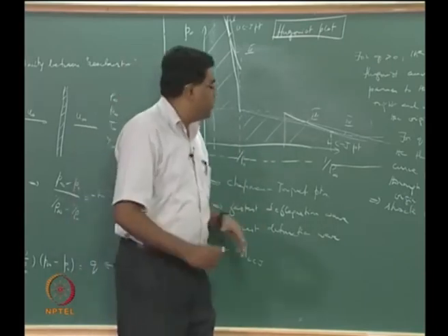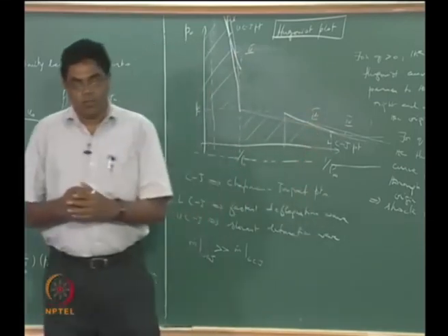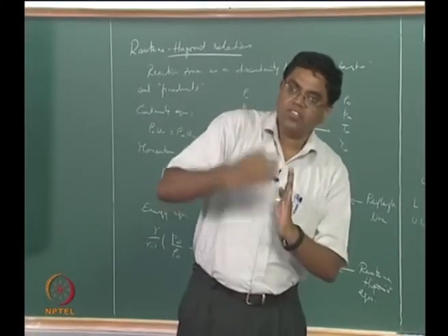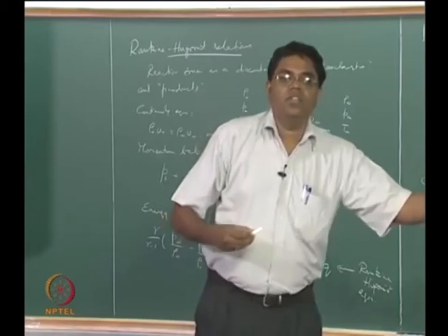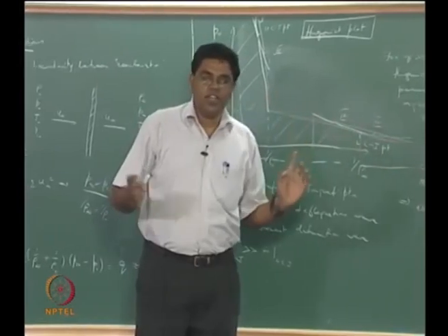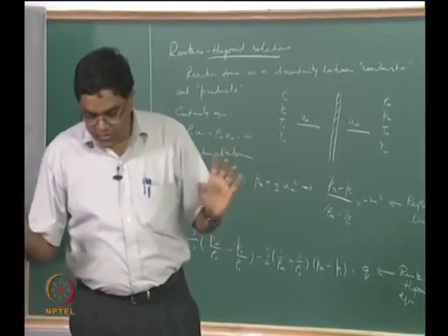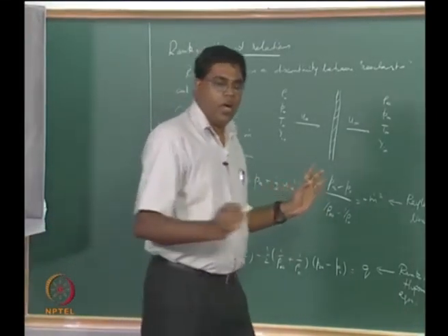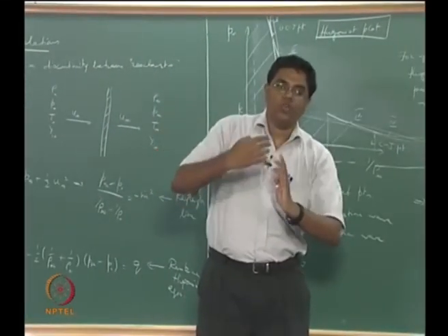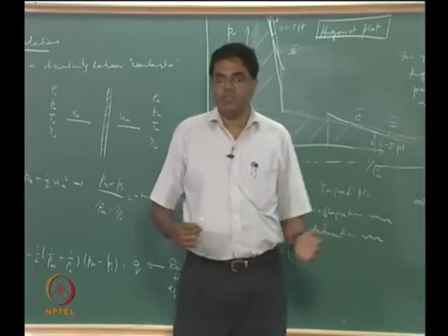Correspondingly, just like how we found in the case of UCJ, what this means for the LCJ is the approach velocities for the reactants is subsonic, alright, but the flow accelerates through the wave to exactly sonic conditions beyond for the LCJ. Now if you really think about it, this is getting a little bit more fascinating, or it's unbelievable, fantastic. Okay, how can I have a wave that started out to be subsonic go through a flame and accelerate so much as to become supersonic? Is it possible for me to do so?